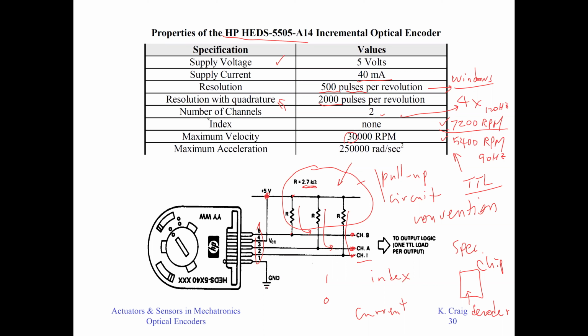Your disk drive usually samples at several thousand hertz level. But now, how many do we need? We need 30,000, one order of magnitude higher. So this is not possible. You cannot imagine handling this with a potentiometer, right? It's not possible. It will damage it immediately. And the shock, this is a huge shock, measured in terms of G.